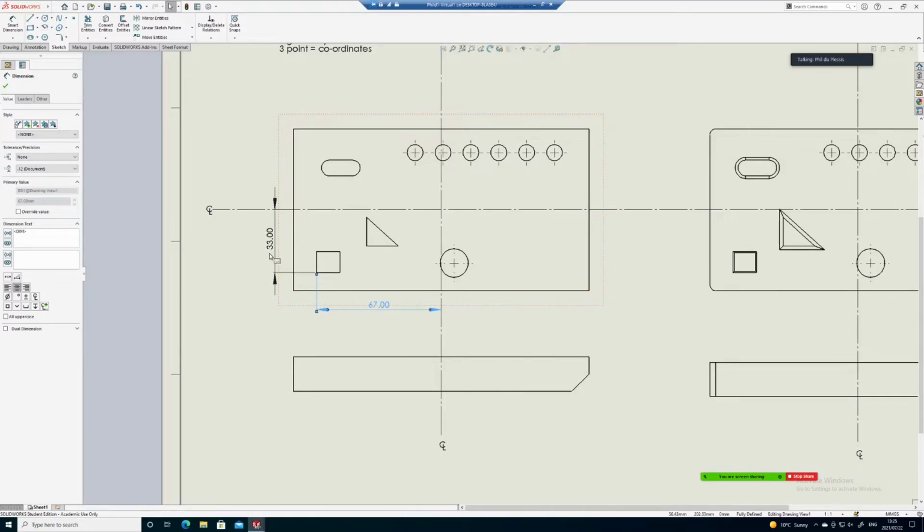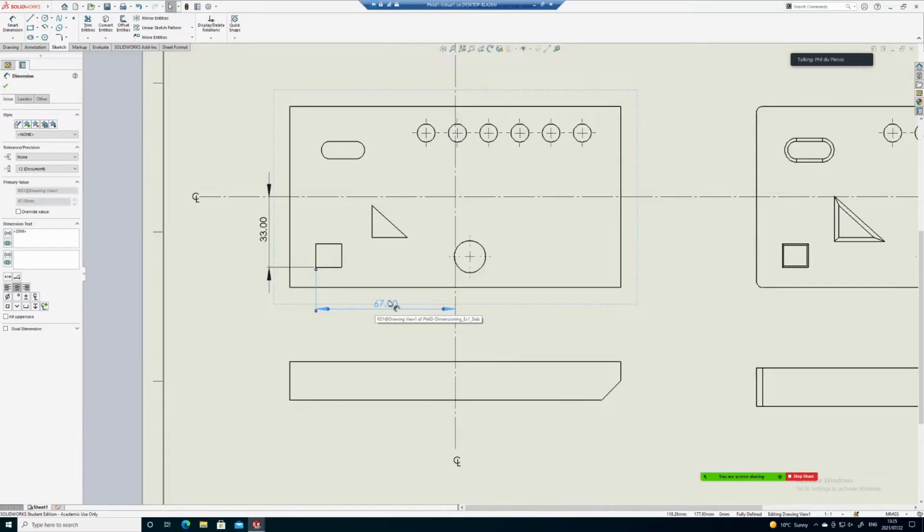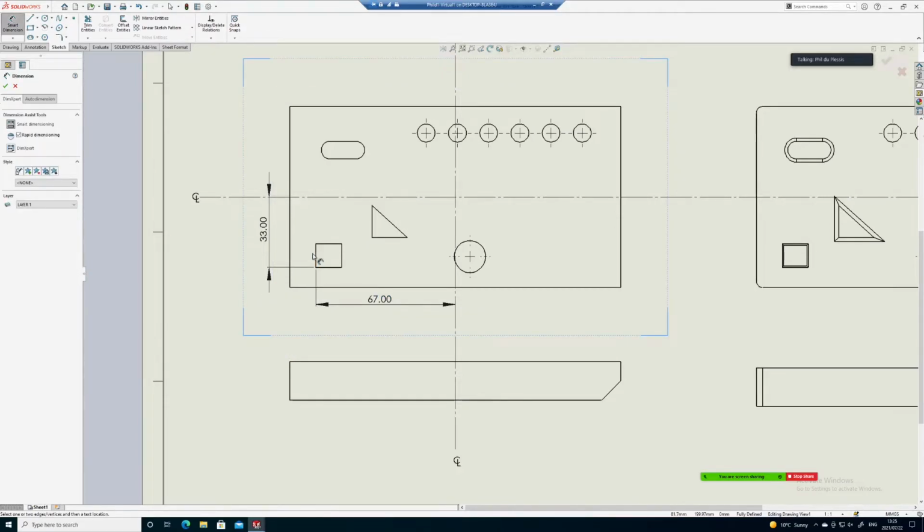Right. Once you've got a position established. So was that Hamza's question about where do you start? Whoever's it was, it's a good question. It really depends on what your aim is. For now, don't worry about exactly where you select the position. That depends on what other parts interact with this part or not. Just know that you have to have position dimensions. Once you've got your position dimensions, you can put in the geometry or the size dimensions.